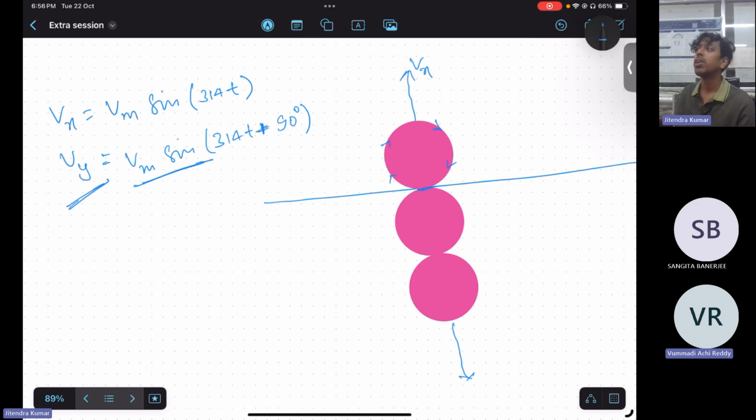Still, so now I'll tell you one trick. Okay, not one trick. Just, once you have figured out the Lissajous pattern of one circle, it will be same no matter how many circles there are and wherever that is placed. You can shift your CRO values, you can shift your CRO waveforms.